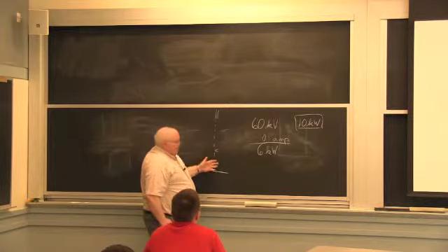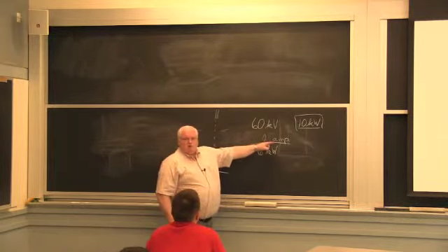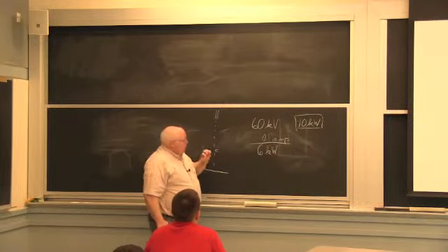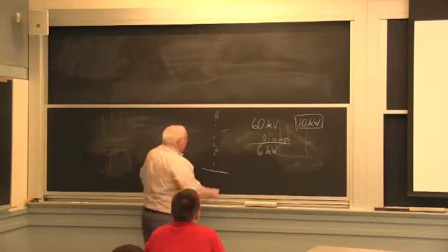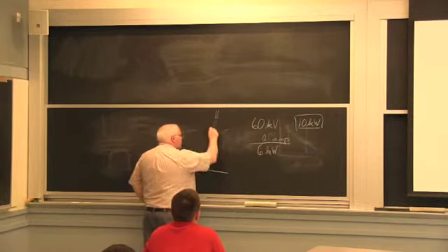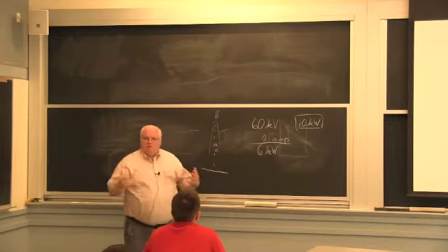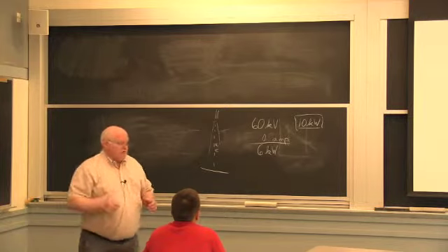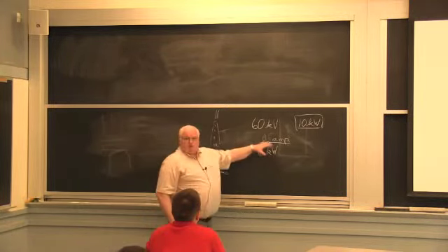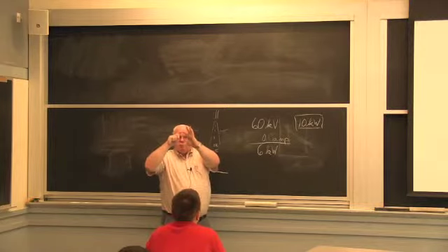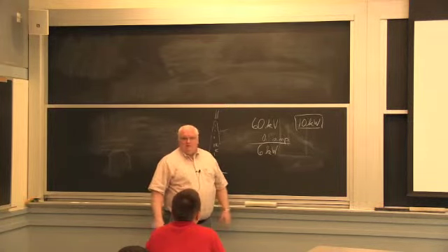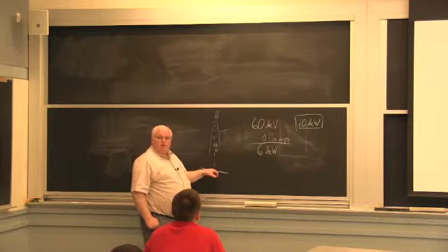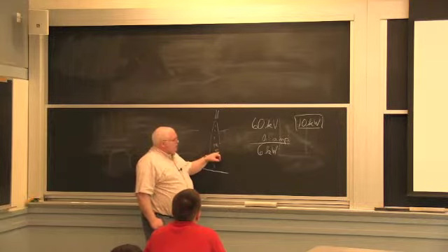And you start calculating these currents and how close these electrons are in that beam, and you find if you get up to 3/10 of an amp, the electrons are so close together they start defocusing the beam. The mutual repulsion will cause defocusing of the beam. So there are plenty of electron beam melting furnaces out there that use 3 amps but have a spot size this big, because you don't care about the spot size if you're just trying to melt. But if you're trying to do a weld, you want a very sharp spot. And you can't focus very well